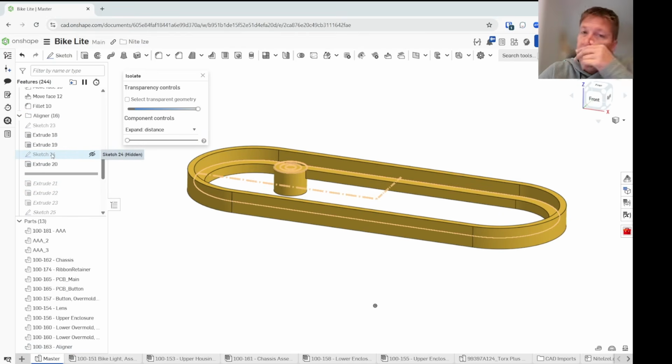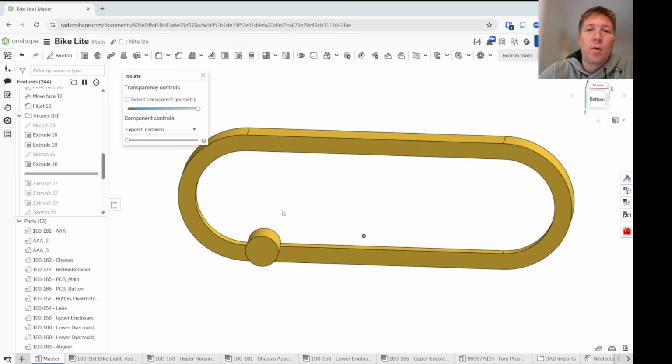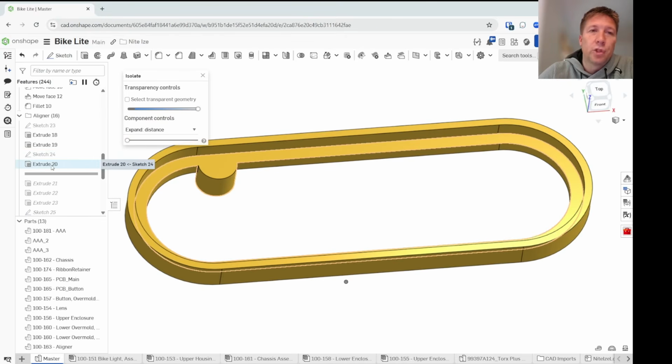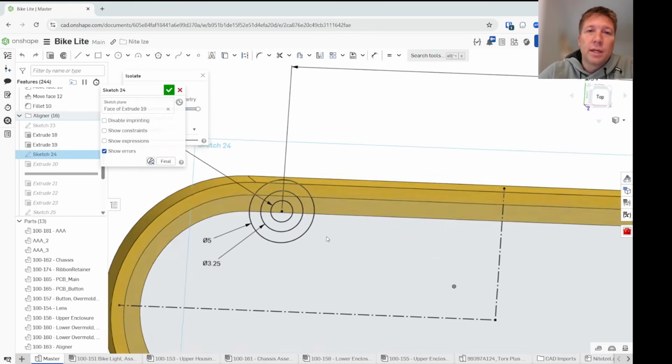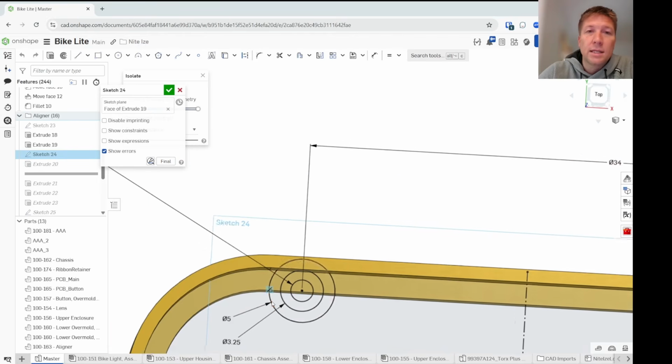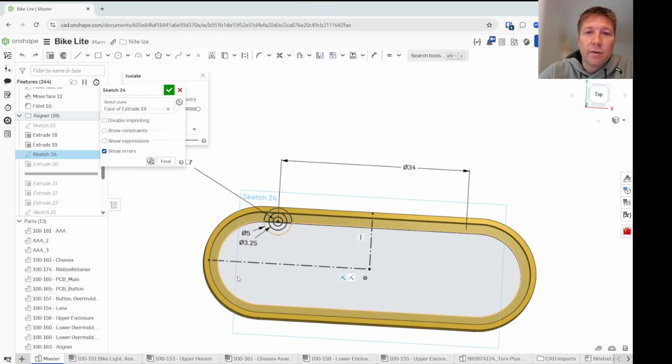And then I create a sketch on that plane where I'm going to go ahead and draw one of the screw bosses, and then I'll do some mirroring to push it around. So what I did is I created one sketch entity which shows the inside screw clearance, the outside screw head clearance, and then the outside of the boss. And then I also defined it relative to two construction geometry lines, so that I can use those to help me mirror this feature.